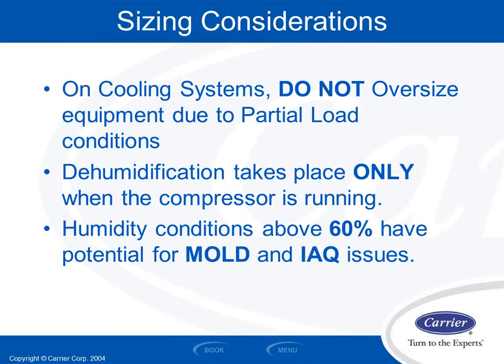Because if I had the right humidity in the space, I could probably make you comfortable with 75-degree air or higher even. And if I don't have that in the space, people tend to make themselves comfortable from a moisture standpoint by driving the cooling set point down on the thermostat. So really cold set points are usually indicative that people are trying to dehumidify their space, and the only way they know how is to keep jacking the set point lower and lower and lower. So correctly sizing the equipment will prevent a good portion of that.